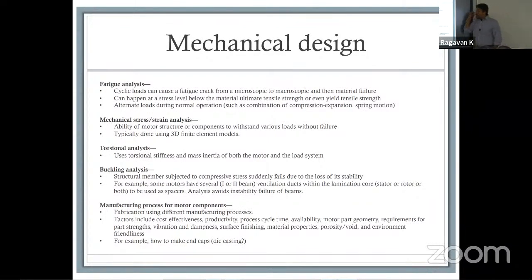The first one is fatigue analysis. Fatigue analysis is the cyclic loads that cause microscopic cracks. That can lead consequently to significant material failures. You can even have things like, if you're talking about the laminations where they separate, right? I don't know if you have seen in motors, sometimes it can get to a place where they separate, in which case all of a sudden your field distribution is not as uniform as your original design was.